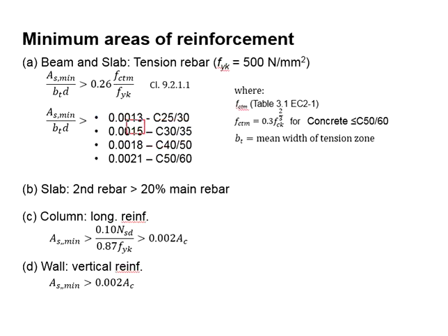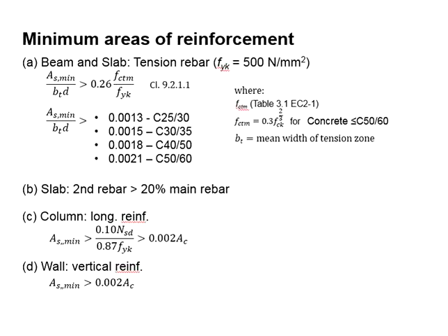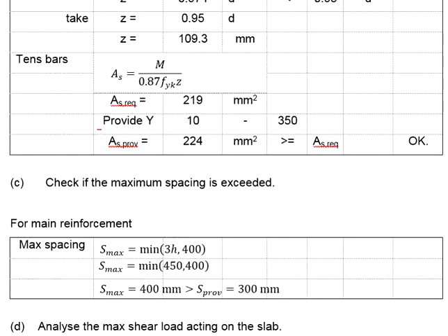That means 0.15% of the effective area of the slab shall be the As,min. Again, the b is equal to 1000 and the depth will be equal to 115 as calculated earlier on. You may compare the As,min found from the equations against that found based on the ratios. They vary slightly. To be safe, you use the bigger value of the As,min to be checked against your As,provided.